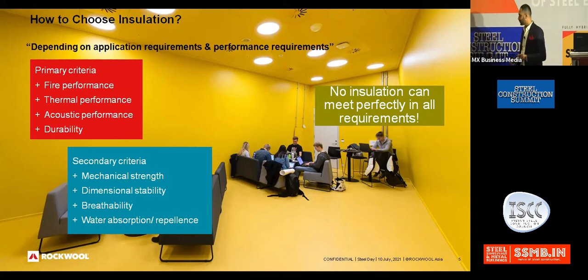Thermal performance, it is a porous material with a lot of air pockets inside. So it absorbs the heat, and that's why the thermal conductivity is as low as 0.033. Acoustic performance, again, it's an open cell material, so it has the capability of absorbing sound. So the noise reduction coefficient of the material itself is more than 1.0, which means it absorbs 100% of the sound.